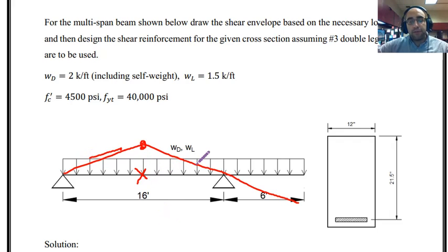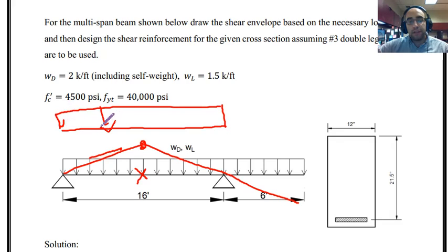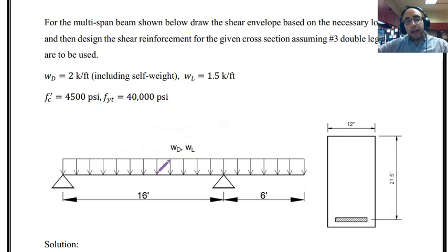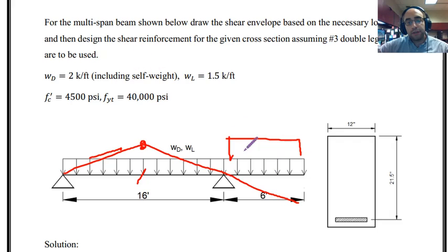And based on this influence line, if I want to get the maximum positive moment at this point, I have to apply the live load in this region like this. And then if I want to know the maximum bending moment over here, I have to apply the live load in this region. Right? This was the discussion that we learned about